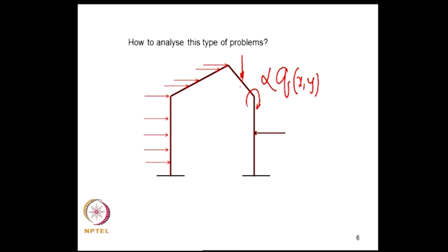After we do that we get the reduced structural elastic stiffness matrix and the reduced structural geometric stiffness matrix. Then we do the eigenvalue analysis and find out this alpha, which is in fact lambda, to get the idea about the condition under which the structure loses stability.